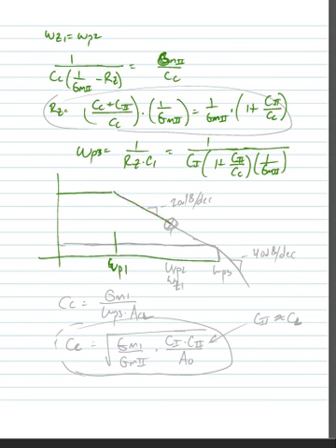We get a roll-off. Now we're causing a pole-zero cancellation at what our original second pole frequency was, so that we get no net change, and ultimately our system comes to our third pole frequency, omega p3, where we now get our new roll-off.